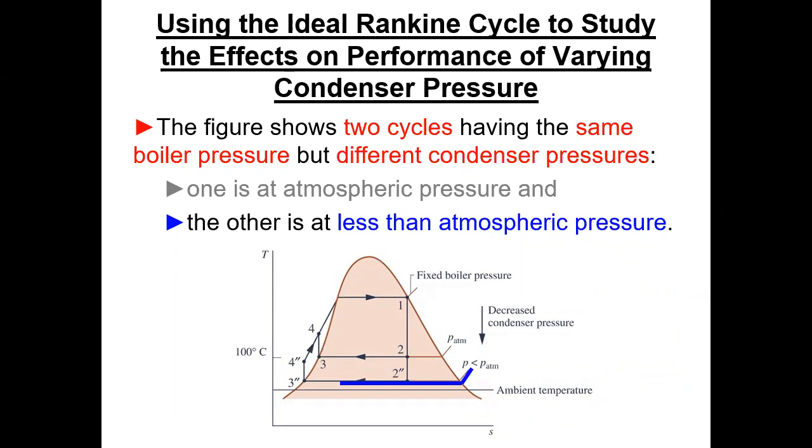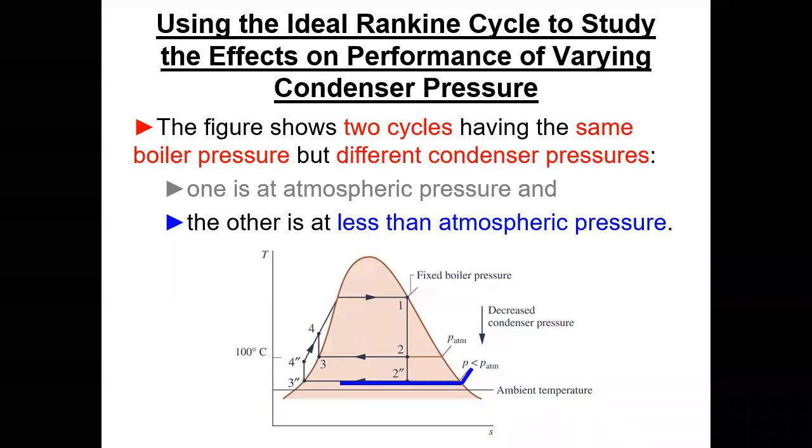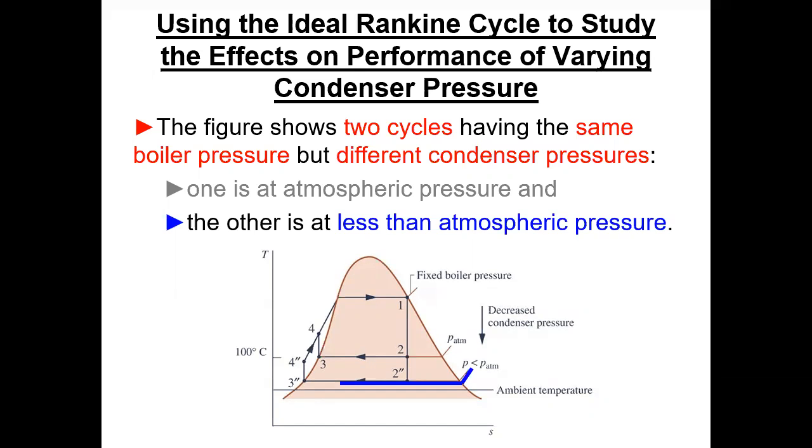And so if you compare two units, one sitting on a lake and one just out someplace that has a cooling tower, a cooling tower can't produce nearly as low temperature water as the lake can. Okay, so in the summertime, you may be lucky to get 80-degree water. Well, your lake is 60, 65, so you've got 15 or 20 degrees lower. So that water-cooled plant is going to be more efficient than the air-cooled plant. And it goes back to the theory, it goes back to Carnot, it goes back to this diagram. That's just the best you can do.